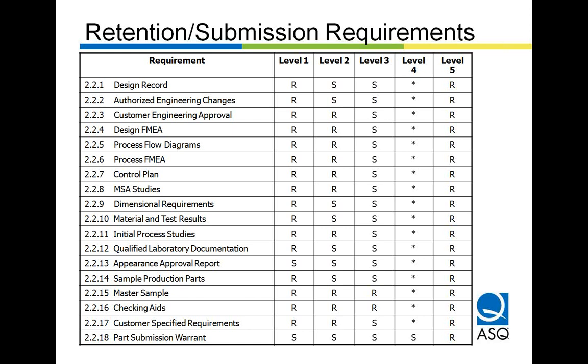In the MSA manual, they suggest that especially if you have, for example, an automated measurement process, like a CMM, so there's no manual intervention that would cause the difference from one operator to another operator, so we have no significant reproducibility error because of the nature of the machine, that we can use the concept of reproducibility to look at the measurement error from one measurement process, say at a supplier, and contrast it to the measurement error that's associated at another measurement process, for example, the customer, and that can be quantified as reproducibility error.